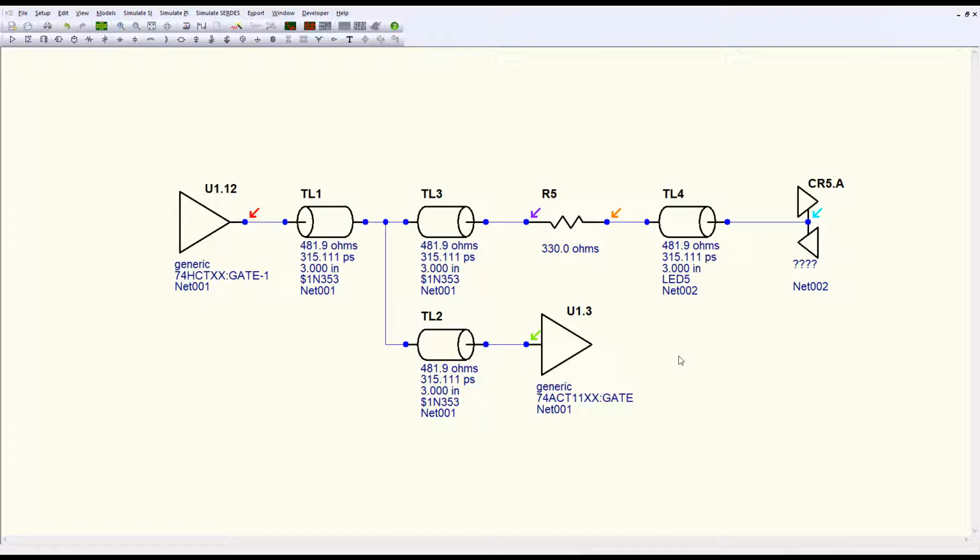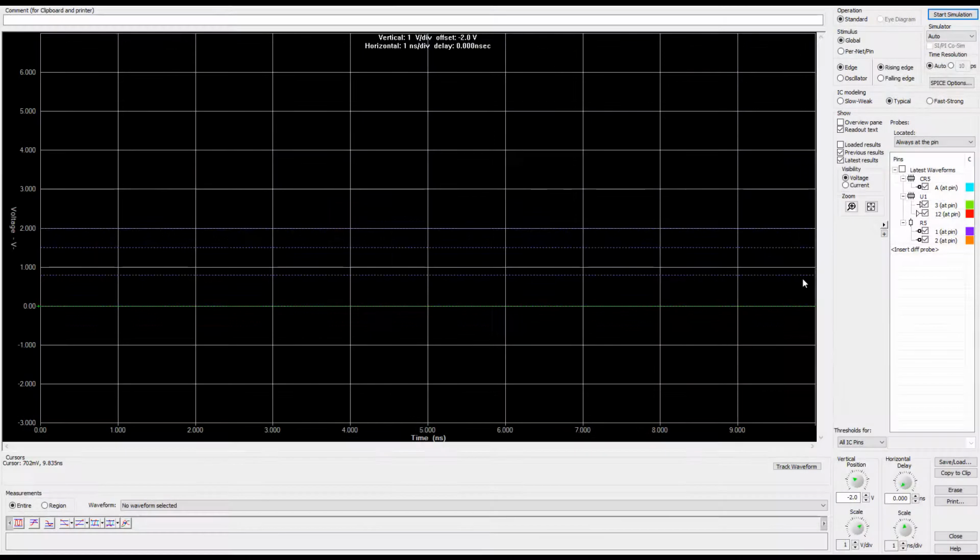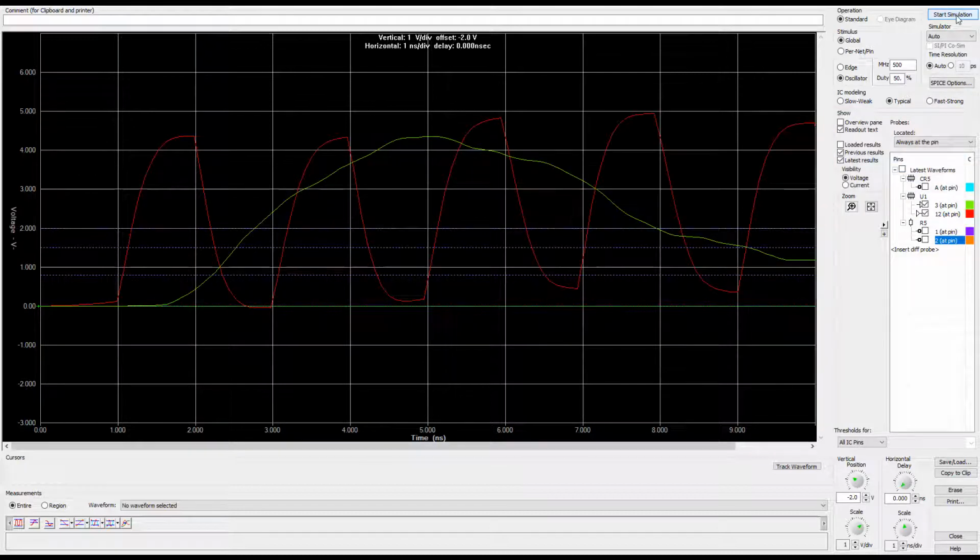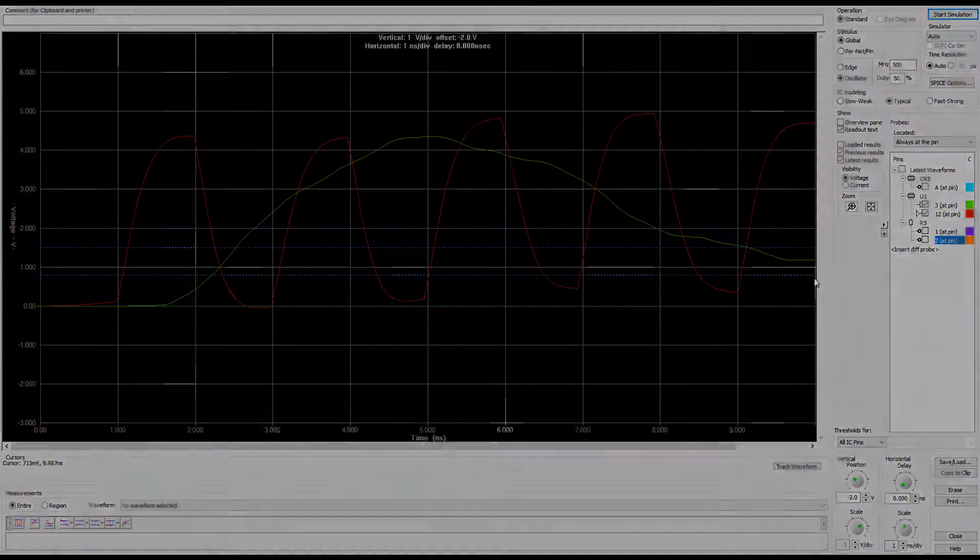Select a net you'd like to analyze and right-click to open HyperLynx LineSim. Here, you can review the models and transmission line characteristics for that selected net. You can even simulate with a powerful oscilloscope. Adjust your oscilloscope to produce fairly realistic results of your signal. Here, you can even model the IC at different speeds to make sure that your design is going to work in all situations.